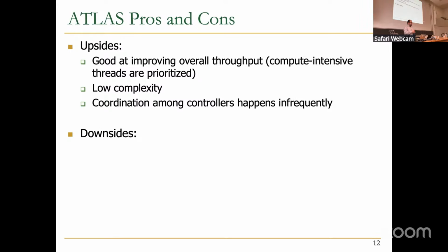That does not let you coordinate the other components in the system based on that ranking. But in techniques like Atlas, you use an interval to learn, and then in the second interval, you fix the ranking. So you have some time where the ranking is fixed, and for that time, you can synergize other components based on that ranking: other memory controllers in the system, maybe also the interconnection network, caches. So you have the possibility to synergize different components in the system based on the ranking that you have done in the previous interval. I think that's also one of the good things about this work, that you can make much more global decisions.